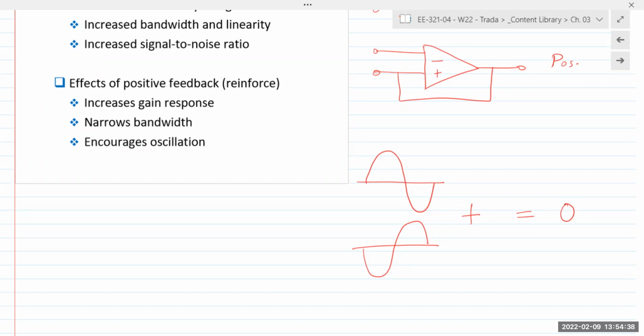You take your incoming signal, you invert its phase by 180, add it to the same input signal, and you zero it out. That's what negative feedback is doing. Negative feedback takes the amplified output, provides it back to the input, so it reduces the input signal at the negative terminal. So that's why the op amp cannot just constantly keep amplifying and drive itself into saturation. Any questions?